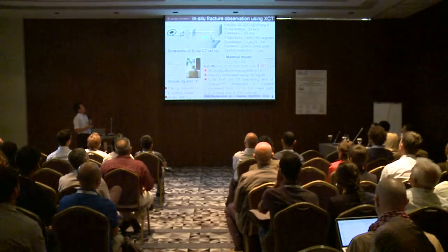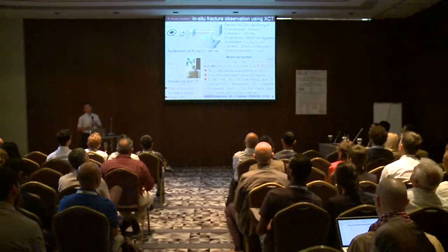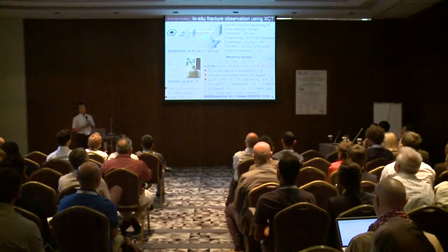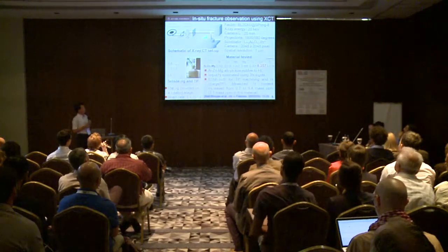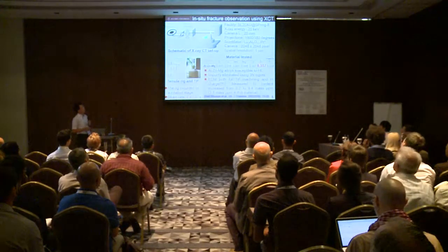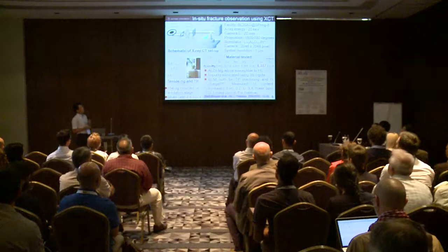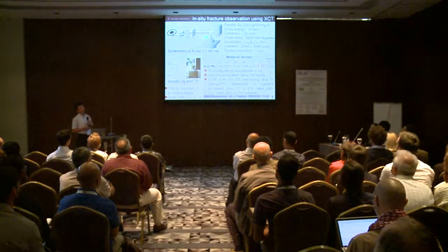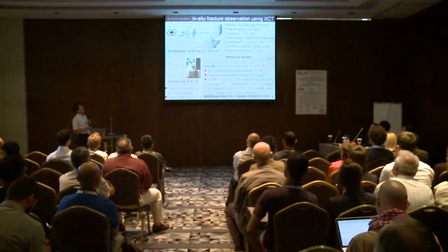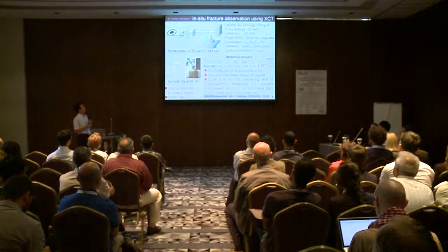The material tested was an aluminum-zinc-magnesium alloy with a zinc concentration of about 8.4%, which is fairly high compared to practical alloys of about 5.5%. In practical alloys, we should reduce the zinc concentration below that level in order to avoid hydrogen embrittlement and stress corrosion cracking. In other words, we may be able to get very high-strength materials if we overcome hydrogen embrittlement for this material. Anyway, hydrogen charging was performed simply by applying the electrical discharge machining technique for sampling this specimen.